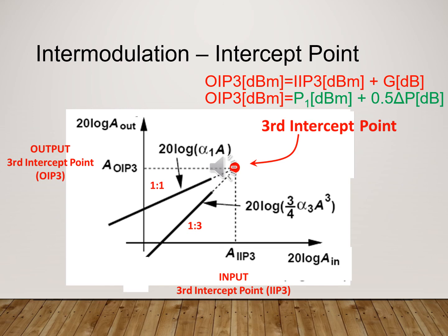But as input signal levels increase, forcing the front end of the receiver toward the saturation nonlinear region, the intercept products emerge from the noise, as you see, and begin to cause problems. When this happens, new signals appear in the band and self-generated interference begins to arise. So we need to warn the customer, or put specifications or boundaries for input levels, to not exceed this point.